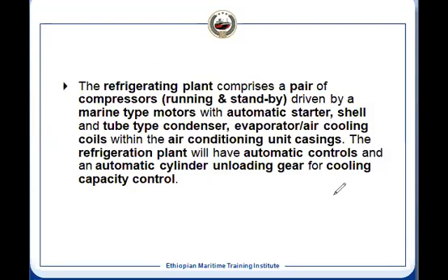this compressor we can have automatic control. What does it mean? Suppose we have the AHU, that is the air handling unit. At the outlet of the air handling unit, we have a thermostat which is measuring the temperature, and we have a set value. We know how much to maintain, and what we do if it reaches that point, that temperature. Usually the air conditioning compressor is continuously running because the load is very high, a high capacity compressor, so we avoid its cutting in and cutting out.